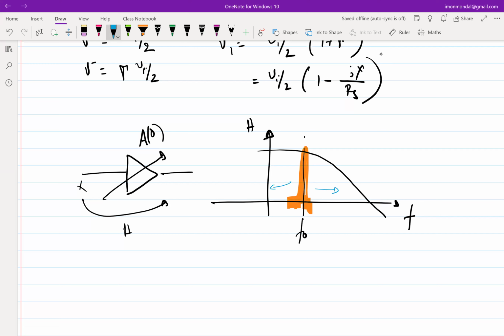This we have discussed in detail at the beginning of the course. So the crux of the matter is that just because you can design a wideband amplifier, it's not necessarily a good thing to put it right after the antenna before any filtering. So there is filtering associated with what you design: there is a SAW filter, then probably a band pass filter, a matching network, which will give some filtering and so forth.